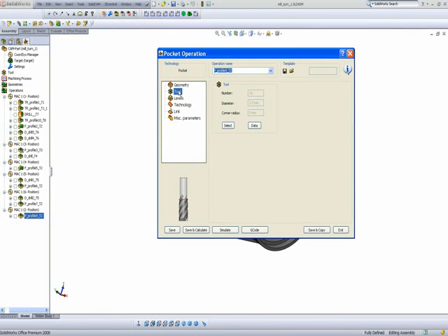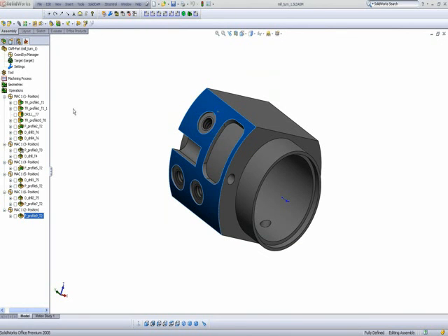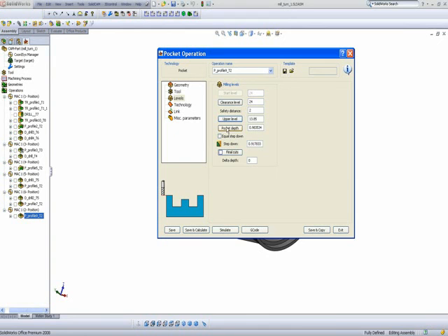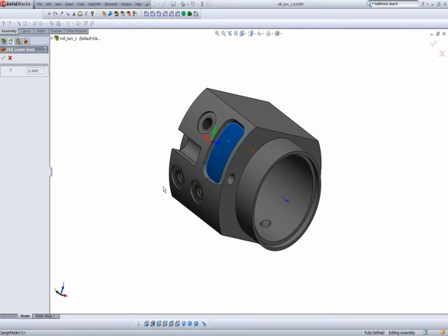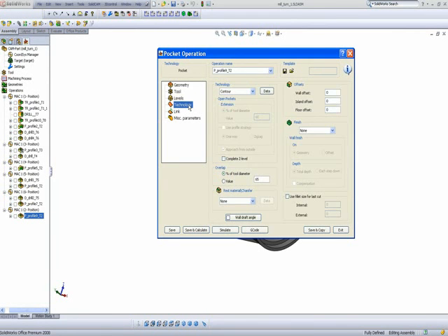Now the tool that I will be using is a 2.5 millimeter tool. My upper level, to do the upper level, all I do is simply click anywhere on the outer surface. And my pocket depth, all I do is click anywhere on the floor of that pocket itself. My technology is the same as any technology in any pocket that I have.